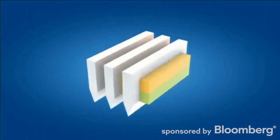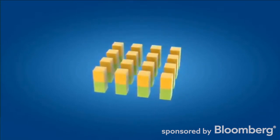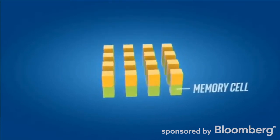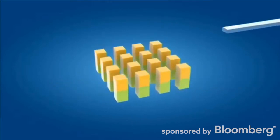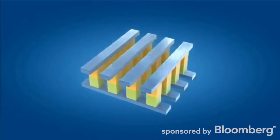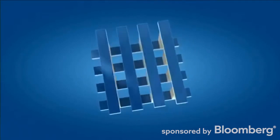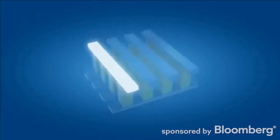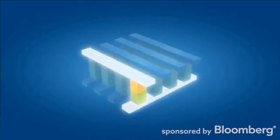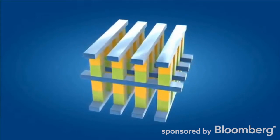We started by slicing sub-microscopic layers of materials into columns, each containing a memory cell and selector. Then, we connected those columns using an innovative crosspoint structure consisting of perpendicular wires that enables memory cells to be individually addressed by selecting one wire on top and another at the bottom. We can stack these memory grids three-dimensionally to maximize density.